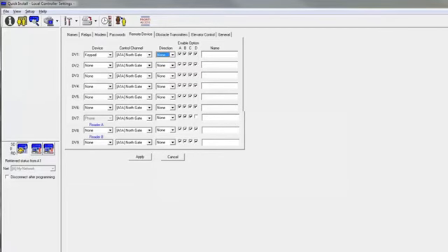That card reader should activate Relay B, or Southgate. Let's select A1B, Southgate, in the Control Channel menu bar. Left-click on Apply, and the panel configuration is complete.